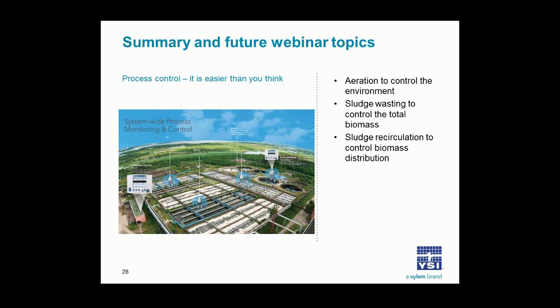With dissolved oxygen, for instance, an online sensor's calibration can last for 2 years. So there you've taken the calibration out of the equation. But also as far as maintenance and cleaning, no longer are we talking about replacing membranes and such. You really just have to clean off the sensor cap or the sensing element so that oxygen can interact freely with that fluorescence layer behind the sensor cap.